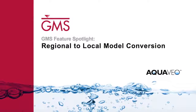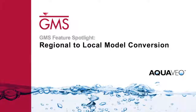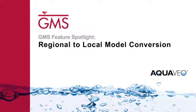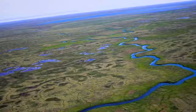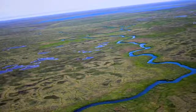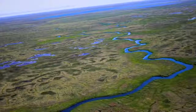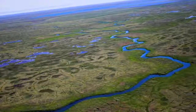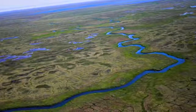For many modeling studies, determining an appropriate set of boundary conditions can be difficult. It is often the case that classical boundaries such as groundwater divides or rivers and lakes may be located at a great distance from the site of interest. In such cases, it is often convenient to first create a large regional scale model that extends to well-defined boundaries.